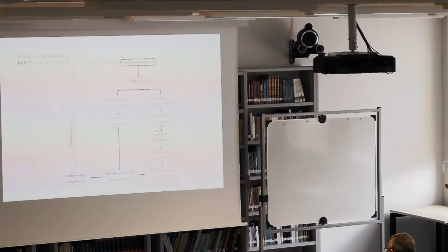For the smaller set, I compute the eigenvalues, and I sort them using a function called MAC. Then I fit my surrogate model to the aeroelastic dampings of the smaller set, and then I run my surrogate model for the larger set, and I predict my dampings and calculate my stability margin and try to minimize the probability of failure using my genetic algorithm.